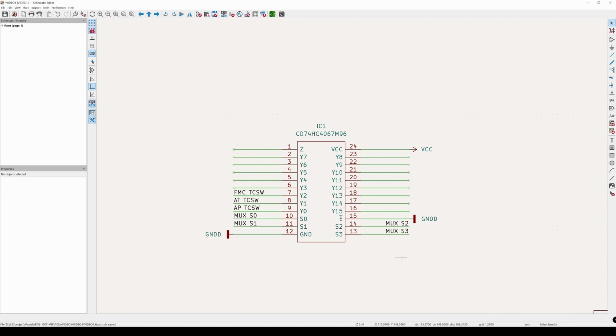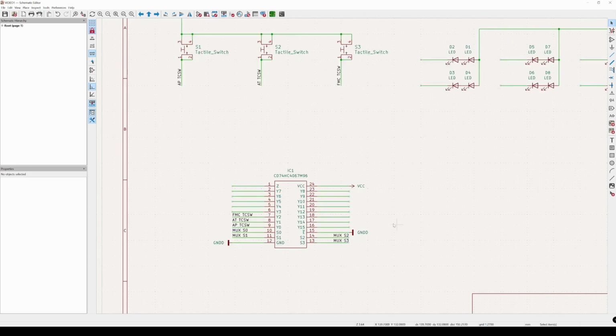So now we have these labels, which will create new nets, and these can be routed to the connector later on, or now if you want to. I'm going to hold off on the connector since there will be much more to add to it, so I'm just creating these ahead of time so that I can wrap up the controller and then move to the next part.